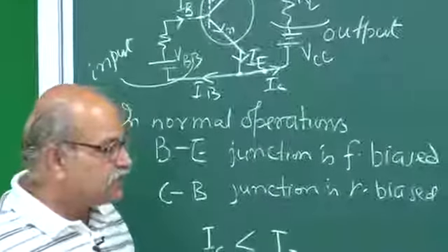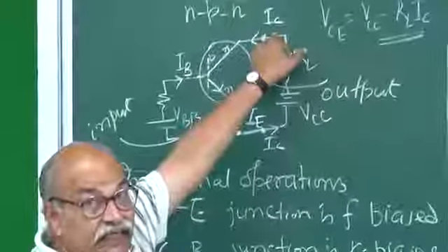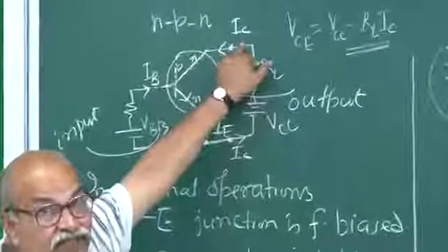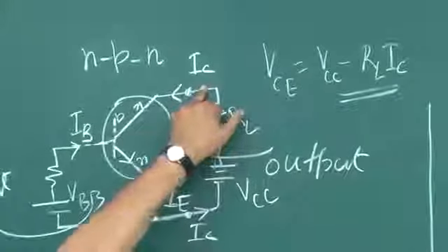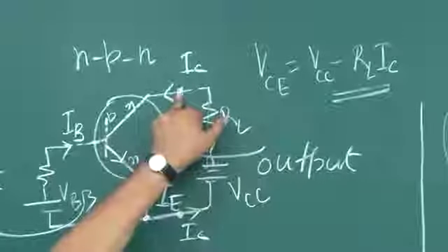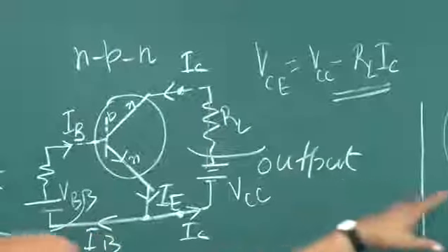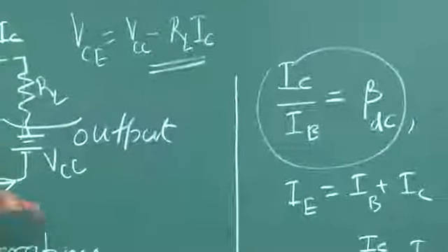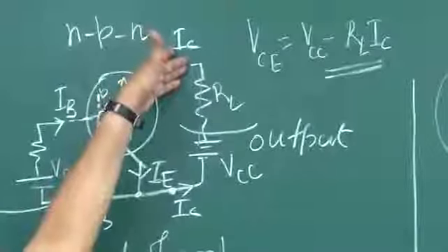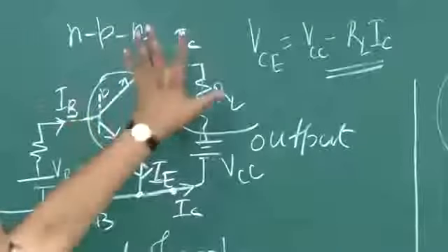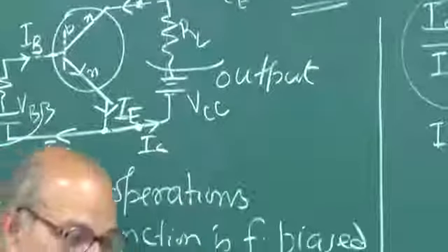And then we have the saturation region, where current is there, the transistor is active, but the capability of drawing more electrons here is saturated. In that case, this IC will be smaller than beta times IB, and if you increase IB, this collector is not ready to respond. So you do have some kind of a constant current after that. These are the regions.